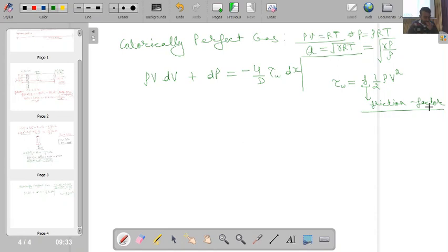So do you remember from your basic fluid mechanics, we have tau w is equal to F times half rho v square, and even you will be surprised, in some places you also use tau w is equal to 4F times half rho v square. Okay, sometimes we use F, sometimes we use say 4F notation. So basically, in order to keep the magnitude same, this particular F has to be equal to 4F in this situation. Okay, so the simple difference is there.